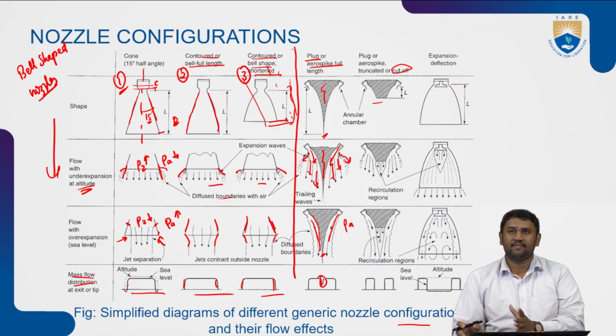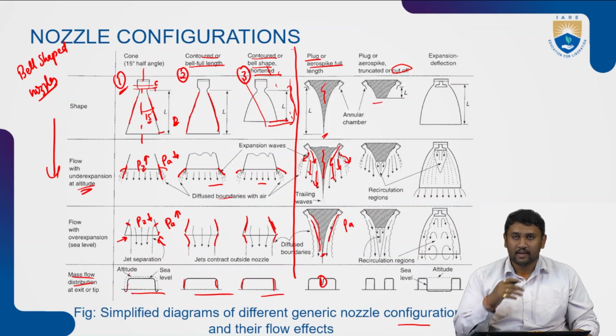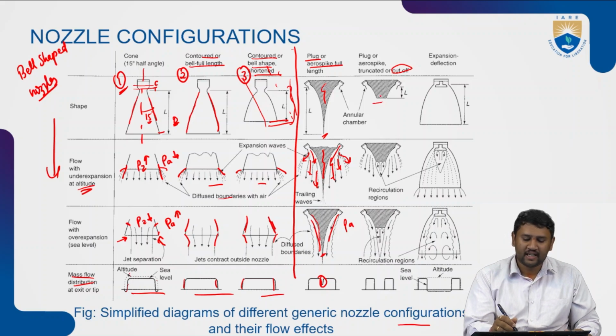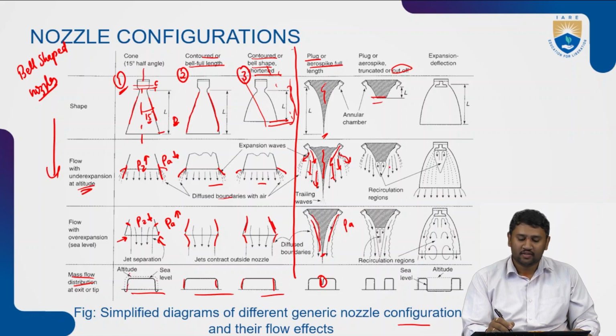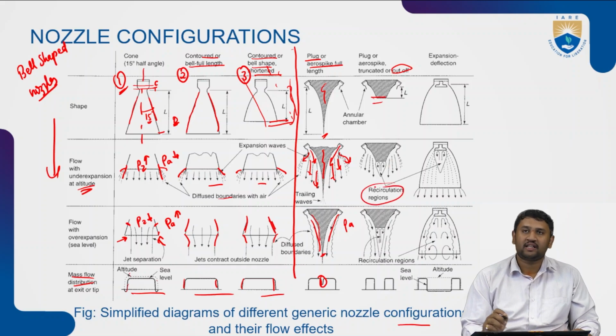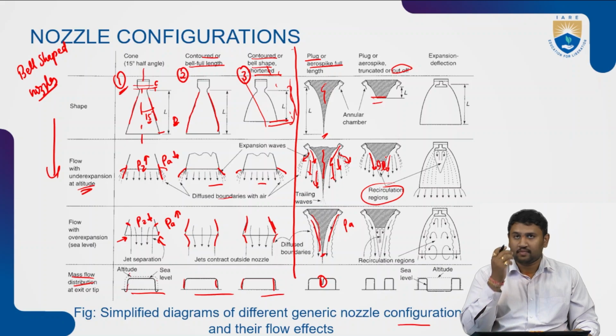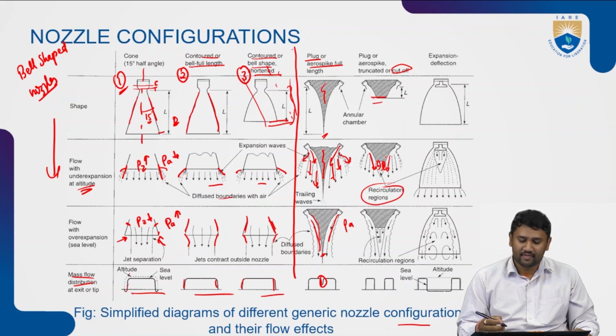Now, considering the same with a truncated one, what happens is basically we will be cutting the length through which the gas is supposed to travel onto a surface, so that you will be creating recirculatory zones, right? A recirculatory region. And what happens under this recirculatory region is basically, as soon as the flow gets out, it will be having some amount of time to rectify itself.